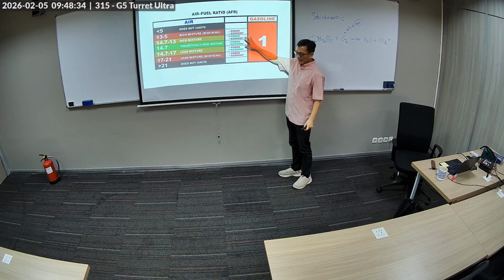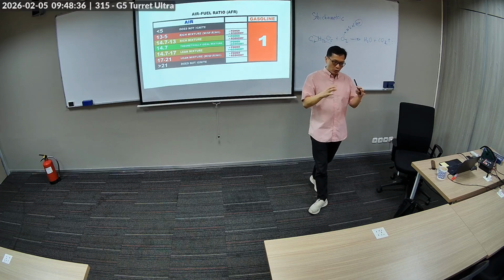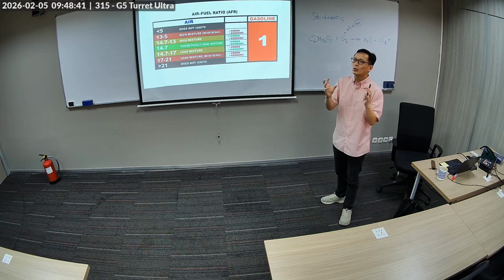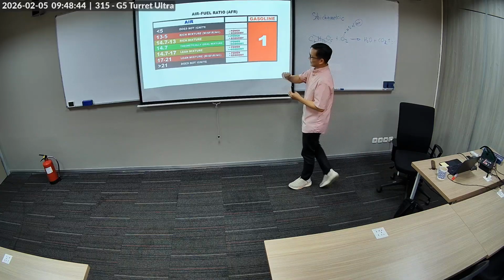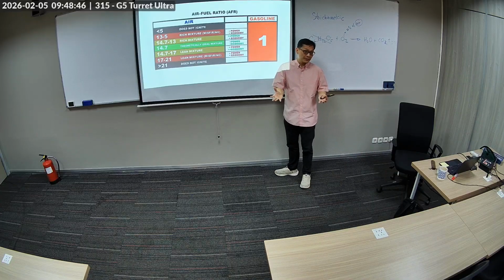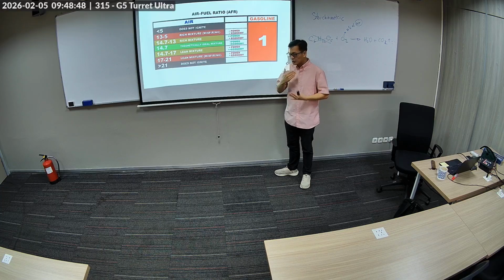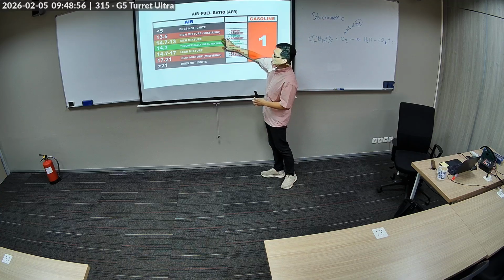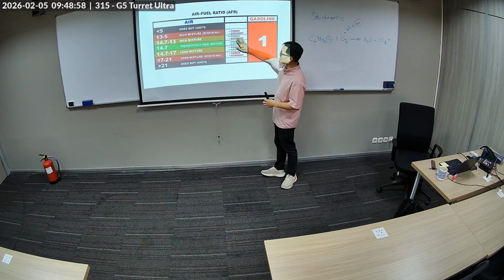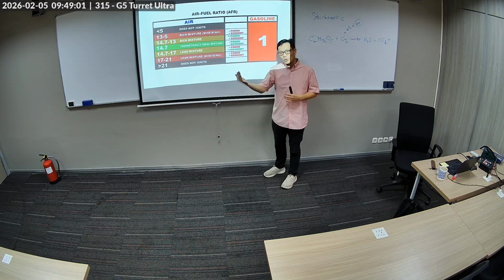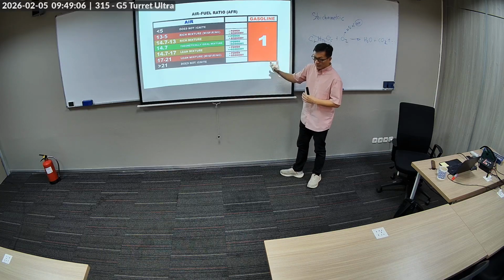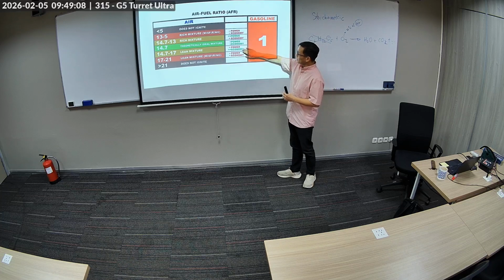If you go richer, it actually cools down the combustion a bit. When I say cool, it's not cool, but it's cooler, just slightly colder. So it's more conservative for your engine, especially I'm talking turbo. It cools down the combustion a lot, and so with boosted systems, you actually go to like 12. So you go even more conservative. If you want to make more power, go to like 12.5. These are all informed by the oxygen sensor, by the way.